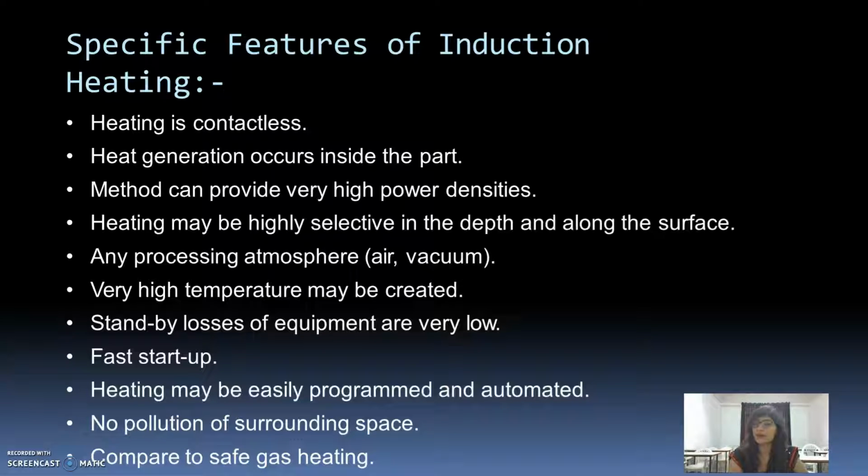Any processing atmosphere is suitable for induction heating. Very high temperature may be created. Standby losses of equipment are very low. There is a very fast startup. Heating may be easily programmed and automated. No pollution of the surroundings takes place, compared to gas heating.